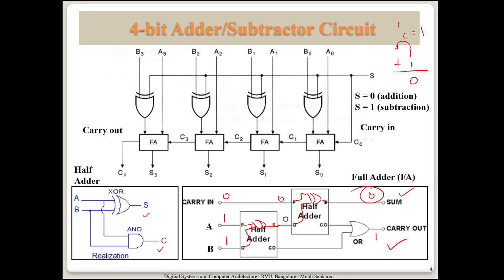Now what about the carry? The same input is given to an AND gate. So let me say this is an AND gate. Both inputs are 1, so AND will be 1 here. Now what about this? Here both are 0, so this AND gate will give you 0. Now you get a 1 here and 0 here, so 1 has come. This is what I expect you to do, and we will give you marks if this is explained and you have drawn this circuit correctly.